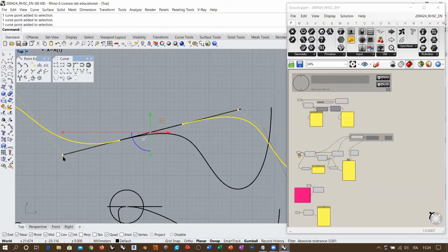Now, if I consider this sequence of 4 control points, what I would do if this was one single command execution, by aligning 4 control points, I am defining this tangent here for this final segment, and then I'm starting on the same tangent, defining the same tangent, but on exit. What happens in between?